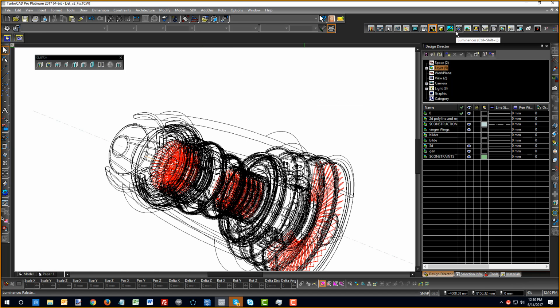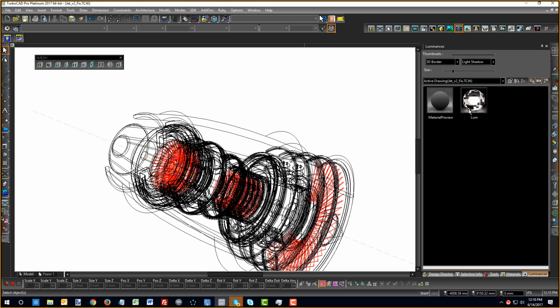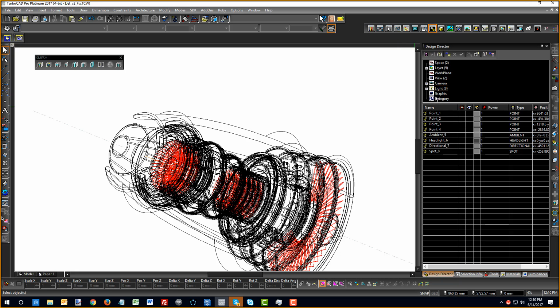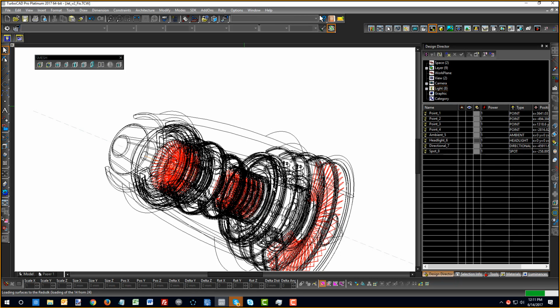engineer it. So if we go into Luminance here, in the active drawing we see the two Luminance objects that he has added. As I was explaining earlier, when I do a draft rendering of this, it's just going to be very dark, because none of the lights are on at all. So the drawing that you see in the forum is done purely through the Luminance objects. And once this comes about, it'll probably be black.